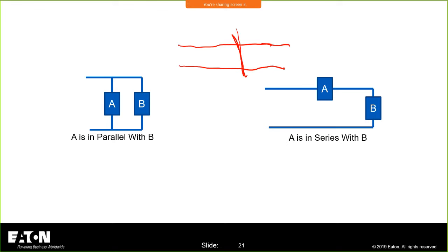They went into a lot of different homes and measured the available fault current at all the different receptacles inside a home, and they found the lowest available fault current that you can have. That is the number in the standards for testing parallel arc protection.